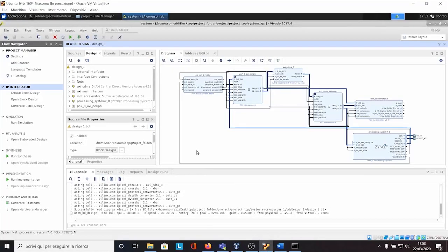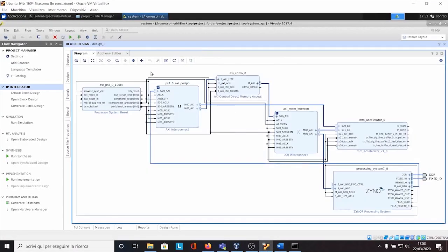We start from the Vivado project generated by MDC. This is the resulting block diagram. Now suppose that our goals are to monitor the latency of the accelerator on doing Sobel filtering, and to perform a runtime verification of the actual runtime transitions happening inside the accelerator hardware. The connection between the accelerator and the CDMA represents the place where we should introduce the hardware monitoring system.